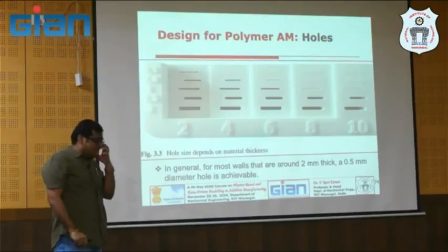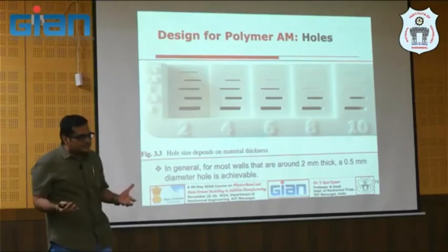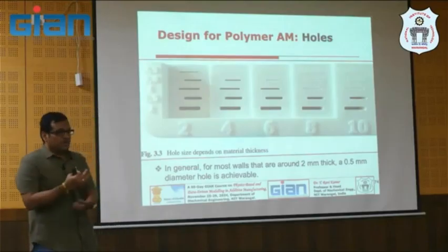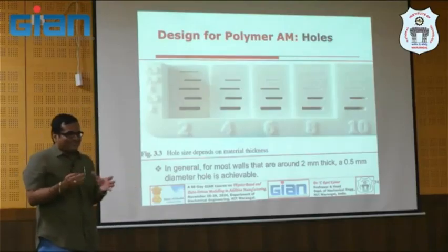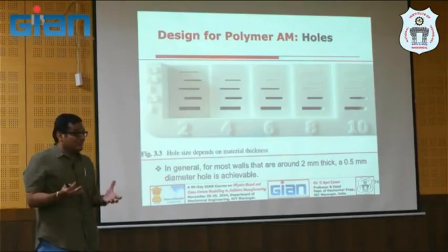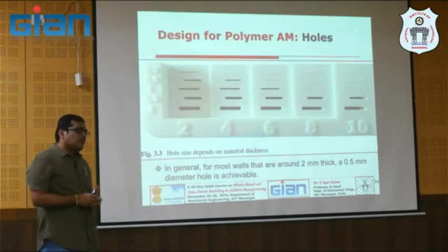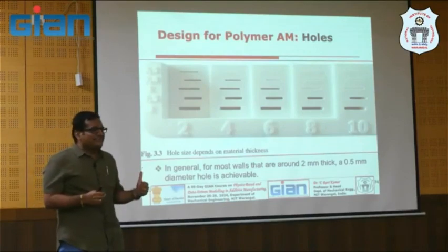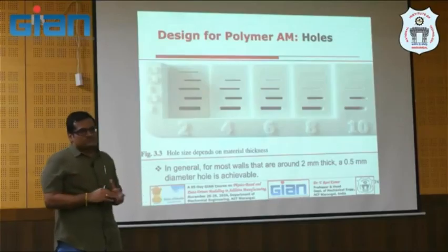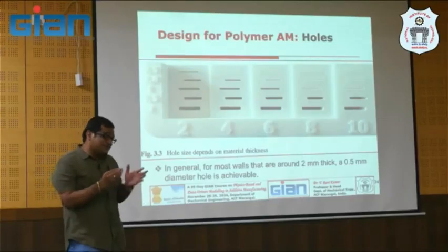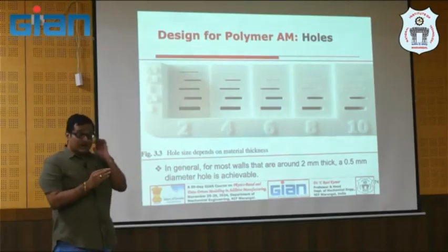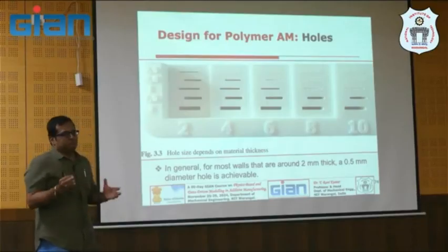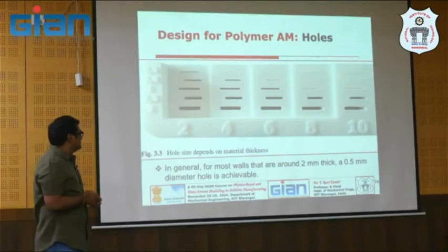Why? Because here the challenge is that all 7 processes will behave differently, right? You have a different energy source and different physics involved, so you cannot generalize. That is the biggest challenge here. If you talk about conventional manufacturing processes, it is not the case. But here each technology or process behaves differently, and within the same process, each material will behave differently. That is what we need to understand.